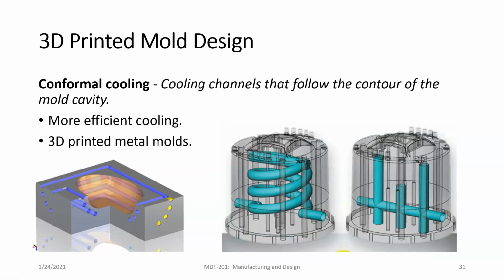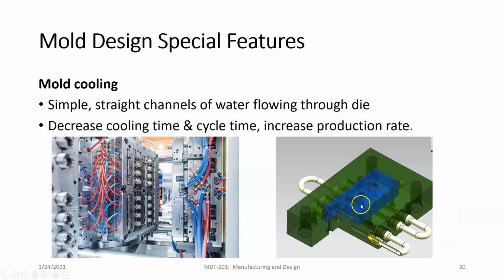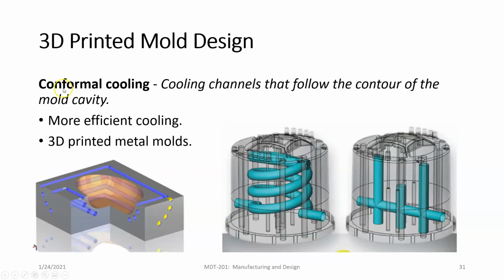What's really neat is there's technology now to do what's called conformal cooling. Conformal cooling is basically taking these straight channels where the water is going to run and making them conform to the shape of the mold, or the shape of the part.